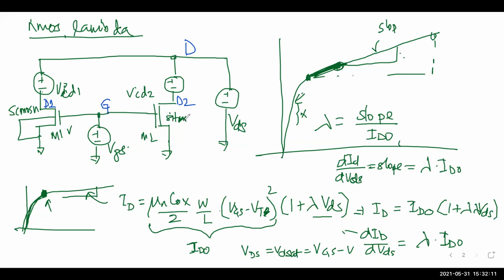So what we'll do is from the previous one, we'll see for what values of VGS we pick, like 2 or 3 VGS values for which we'll get manageable current. We'll use those 2 or 3 values to get a family of slopes. We just need one slope, but I think the problem statement describes how to get a family of slopes. Then we'll measure one slope and get the lambda. Then again, we'll create the model with that lambda, put another device here, and compare it.